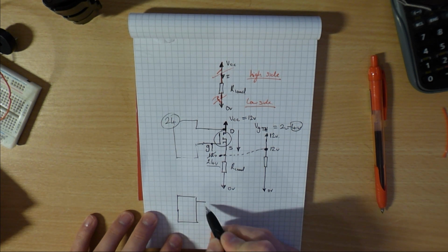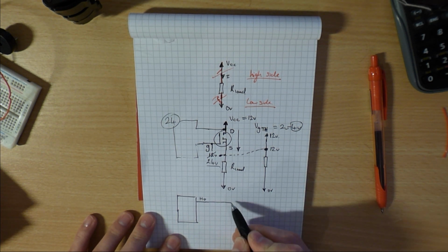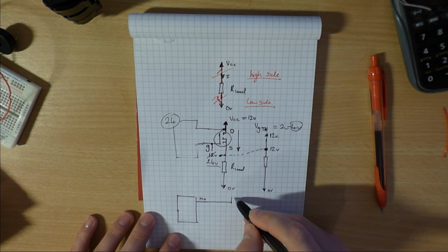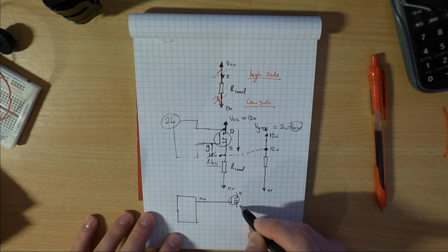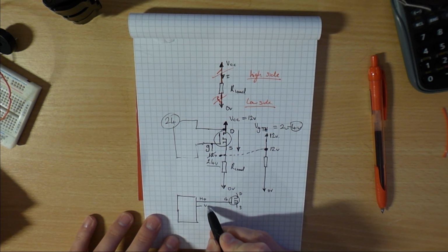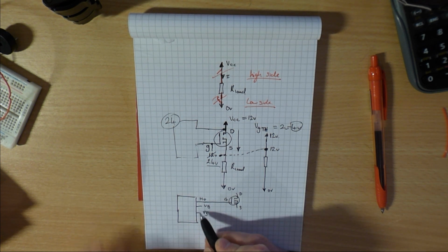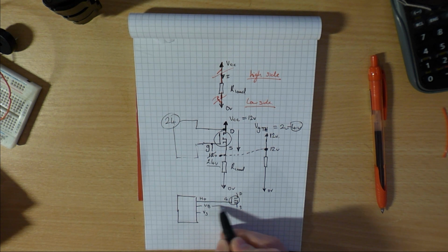it has a H-out output, or HO output, which goes to our MOSFET here, like that. There's the drain, there's the source, there's the gate. It has something called a VB and something called VS. Now what the function of this is you add what's called bootstrap capacitors to this. So there's one capacitor.